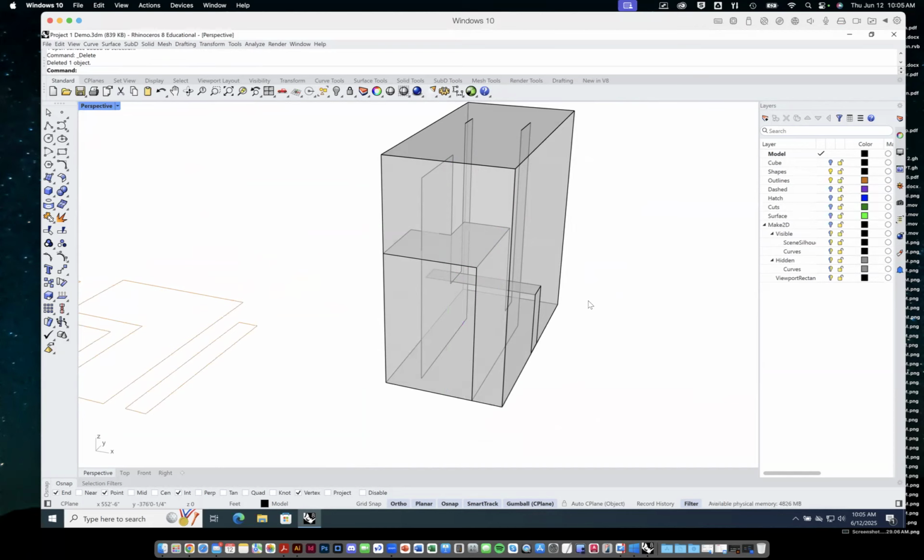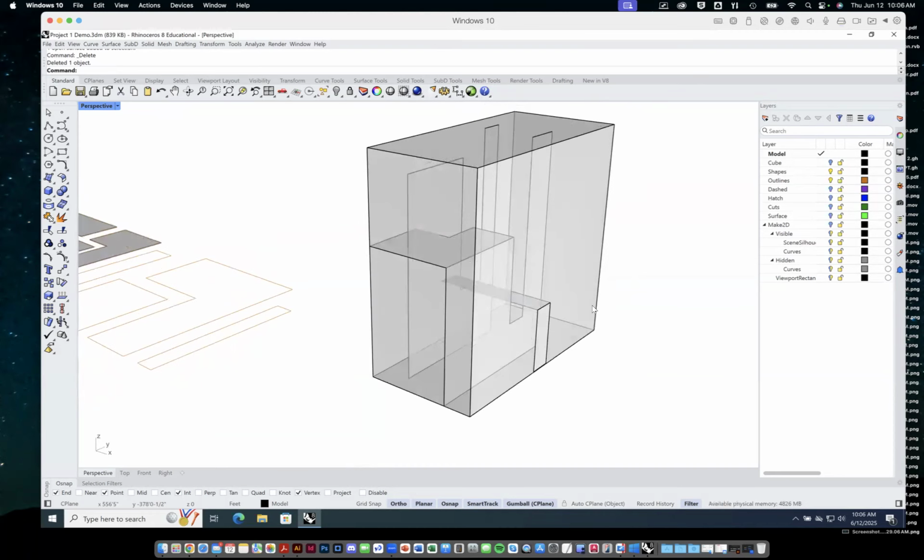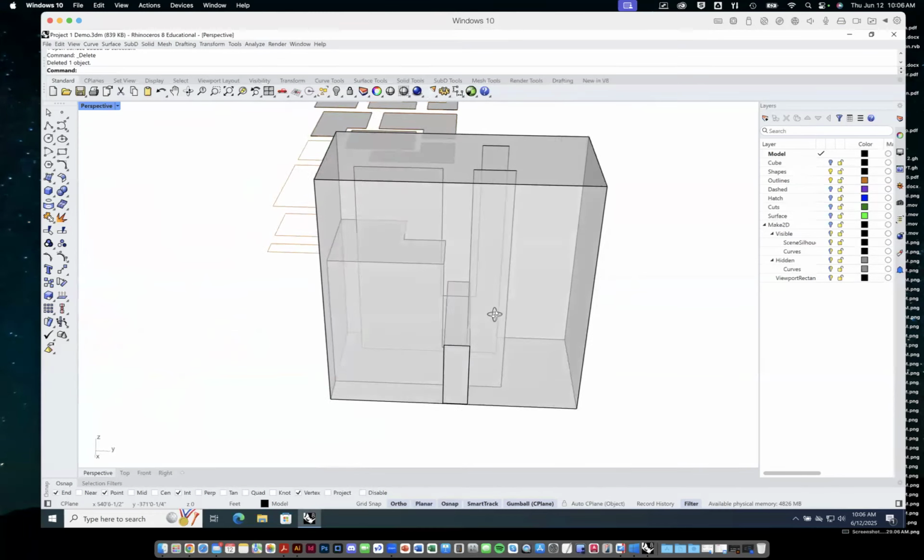Sometimes then I just type in MOVE if I want to snap from one corner to the next and be very precise. And again, you can use things like scale 1D, in order to stretch things just in one direction in order to make alignments. And of course, feel free to trim and split. All of these things are just relatively simple geometric operations. And the more you try, fail, try, make it, try, practice it again, the sooner you pick things up and it becomes really intuitive over a couple of days of using it.